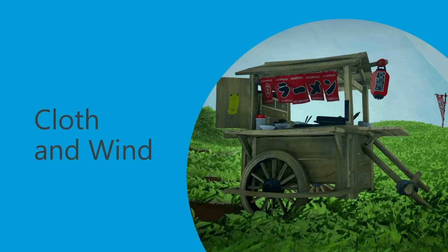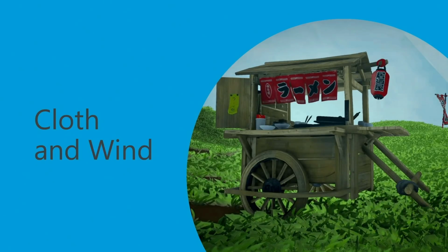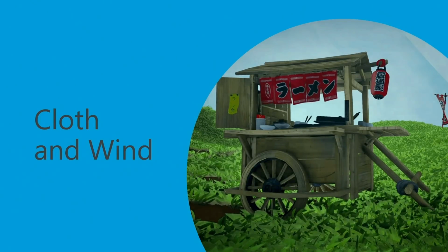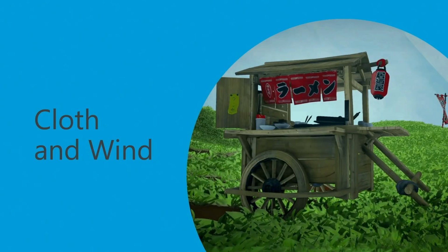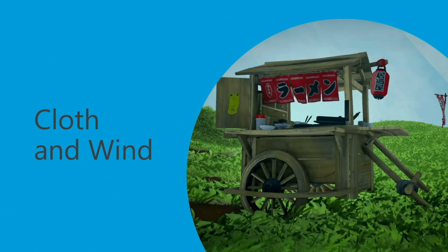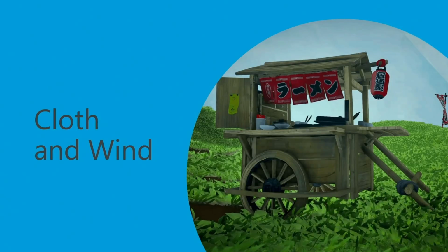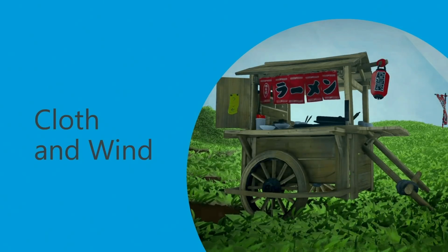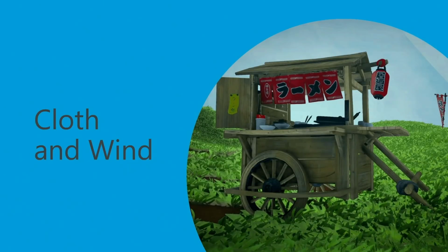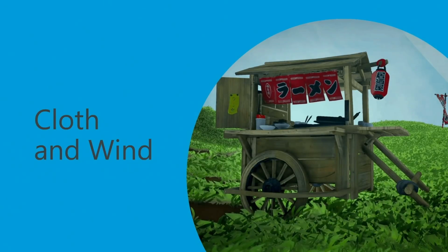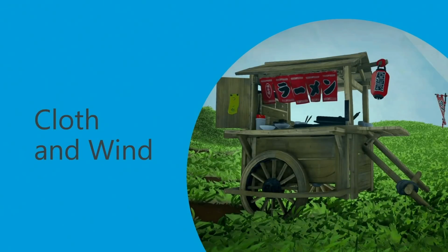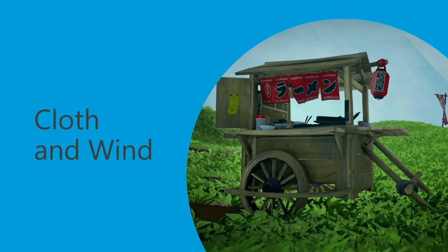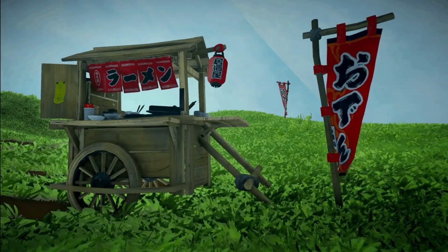So next, we're going to jump into cloth and wind. As everybody knows, Houdini 17 brought in this really powerful Vellum soft body simulation stuff. So we wanted to take advantage of that. But we didn't want to run all of this cloth in real time. We wanted to bake it out into skin meshes that animate but still look very realistic. And along with this, we make use of a lot of Houdini's wind simulations or gas simulations to create vector fields that we use to drive all of our particle effects in game.